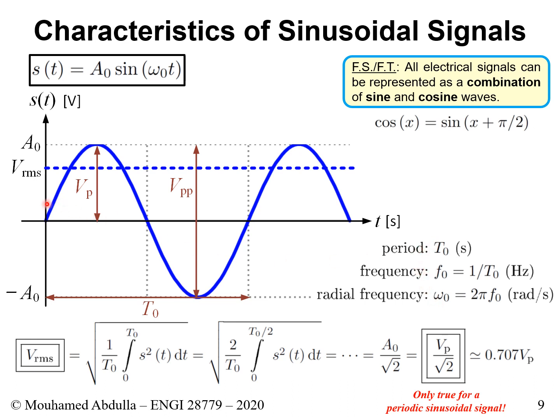On the other hand, if one gives you a figure, a picture, a graph of a signal like this, right away from the graph you could find your T naught, you could find the period here, and once you find T naught, you can find the frequency. You just do 1 over T naught, and once you find the frequency, you can find the radial frequency of it. You just multiply by 2 pi, and then this value, you enter it into some sinusoidal, sine, cosine, doesn't matter. If you do this in an exam, I would accept it. I would prefer that you use sine, but even if you write cosine, for me, it's still fine. You would just enter the value here, and you just put a t in front of it.